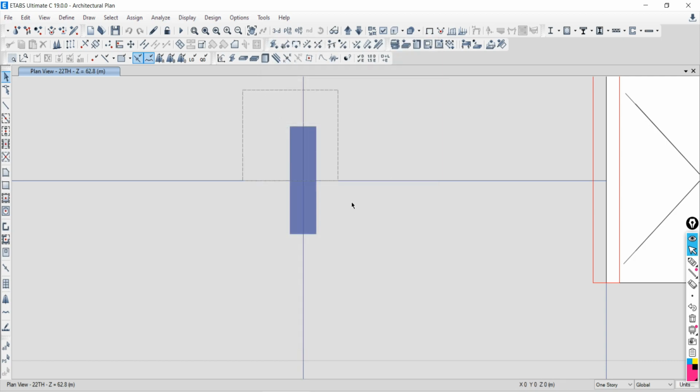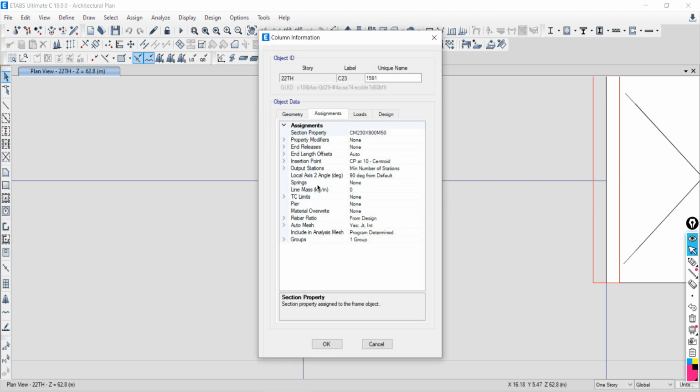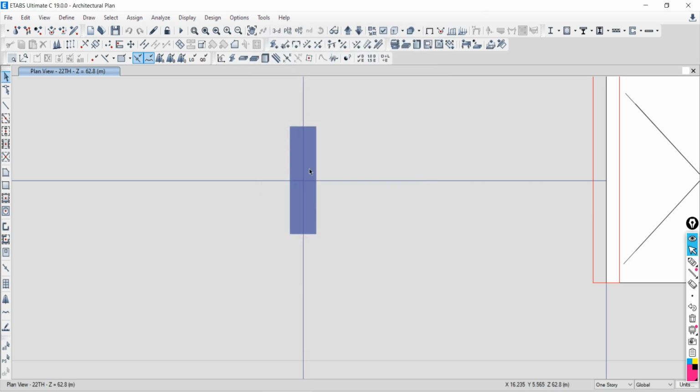Column property. Drag it from left to right. Just right click over the joint. Take your cursor, press the Control and right click on the mouse, and come down to see the property of this column. If you want to make the selection, drag from left to right, let the column come inside this dialog box, so you will have the property selection: one joint, one frame. Is that all clear?